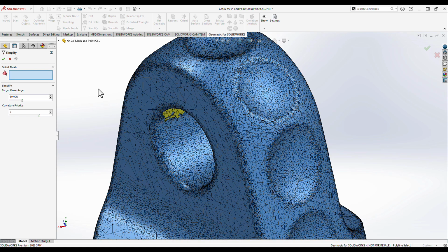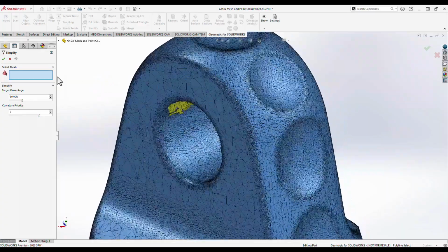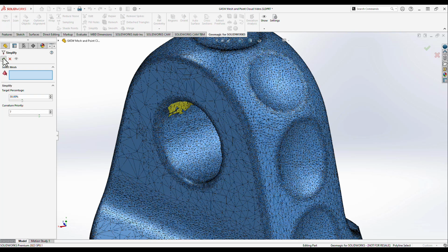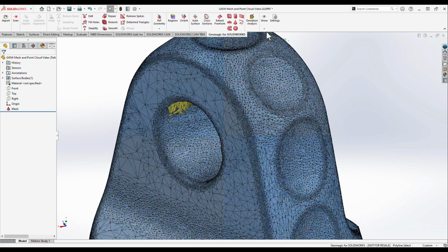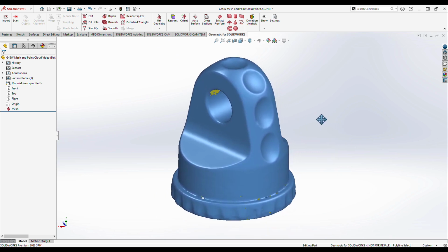Through the Simplify tool, areas of low curvature are consolidated into larger triangles, while the details in areas of higher curvature are maintained at higher resolution by keeping triangle size smaller. This creates a functionally identical surface to work with while using significantly less data to represent it.